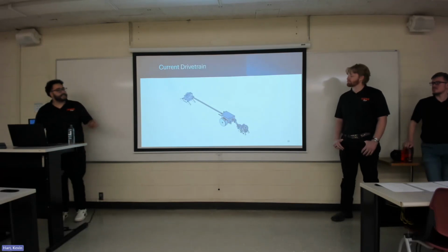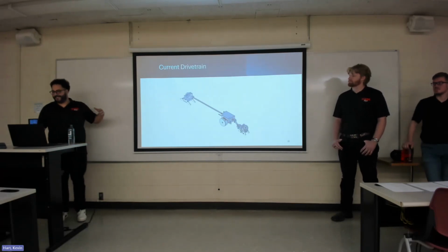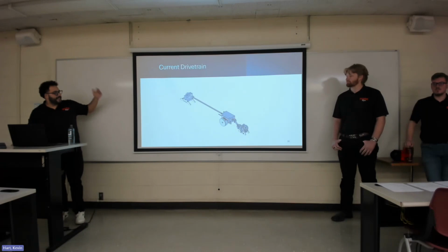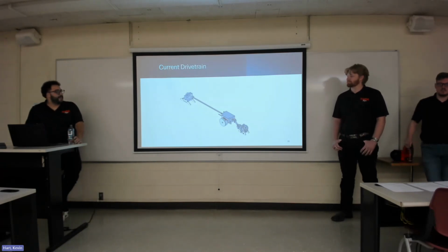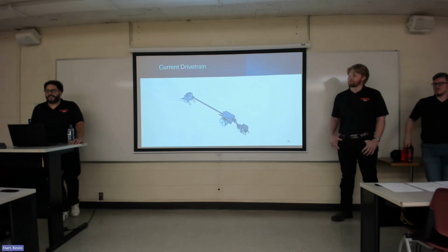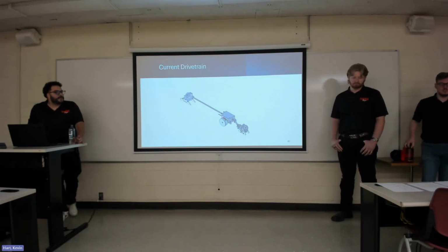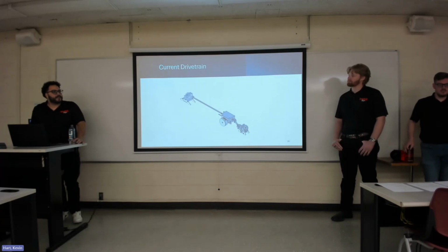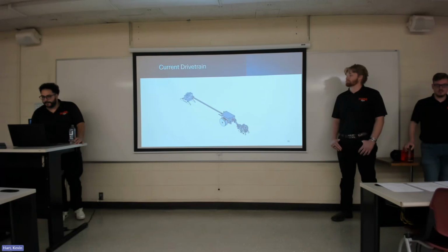And then the current drivetrain, this is the model from Big Red. With this vehicle, we used the CVTech CVT to a 2-to-1 reduction box. And then we used a solid steel drive shaft with purchased Can-Am differentials and Can-Am CV axles, which was, if you know Baja, way too heavy, way overbuilt, not what we need. So moving forward as a team, we really want to focus on in-house design and development. That way we can be prosperous as an organization.